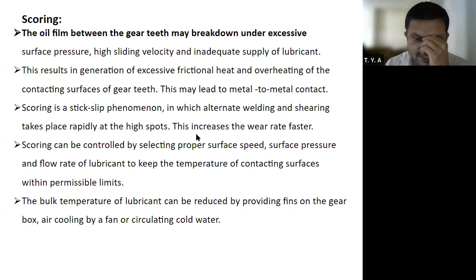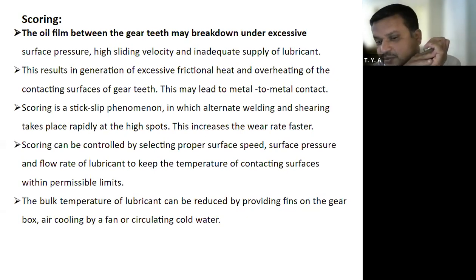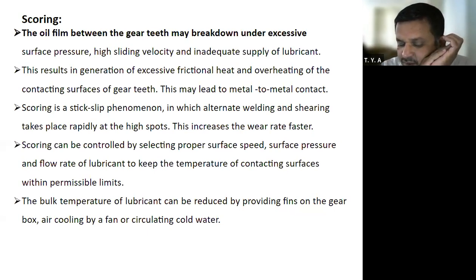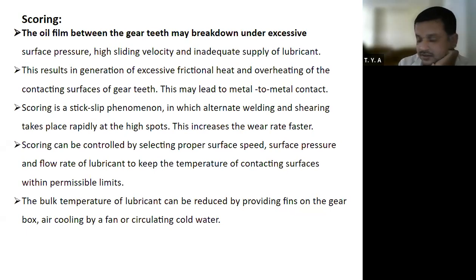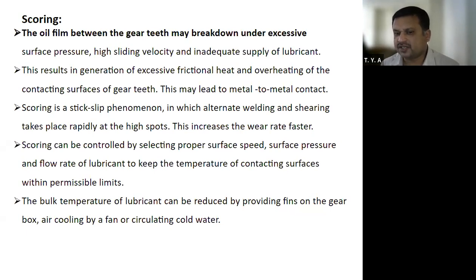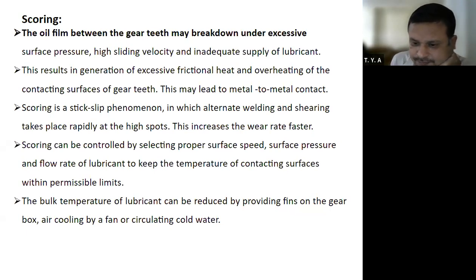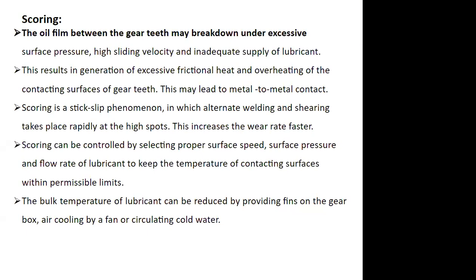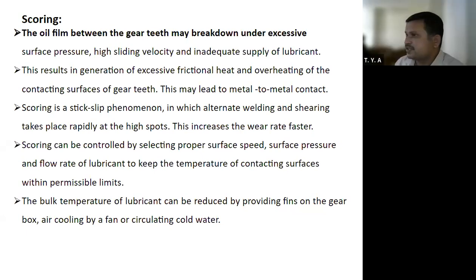Scoring can be controlled by selecting proper surface speed, surface pressure, and flow rate of the lubricant to keep the temperature of the contacting surfaces within permissible limits.